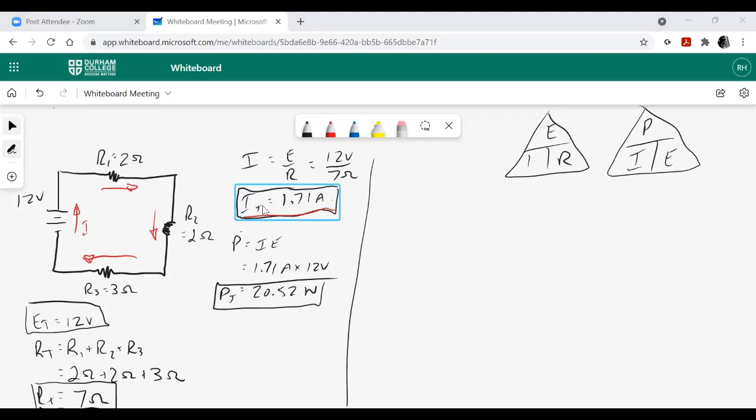What I do with that current number is I'm trying to solve for wire size. So I would take that number and go to Table 2. My choices on Table 2 are 15 amp wire, 20 amp wire, 30 amp wire, 45 amp wire. So whether I rounded it to 2 decimal places or 14 significant digits or whatever your other teachers have been hassling you about, I don't really care, because we're doing a ridiculous amount of rounding once we go to the code book anyway.